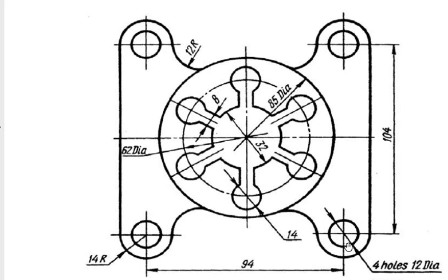After making all these things, using the trim option, trim is TR double enter, we'll remove all unnecessary lines from the sketch. So this is how we are going to make a sketch using AutoCAD. The first thing to keep in mind is what to draw and where to start. This is the procedure of drawing this figure. Now let us enter into the AutoCAD module.